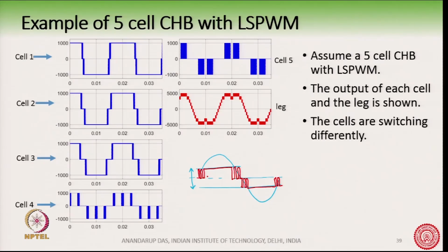Cell 2, for example, is taking this part of the waveform. So, it will be switching here and then it will subsequently get clamped, and this is what cell 2 is, shown here. You see this part till this part, so it means cell 2 sits over the top of cell 1 and subsequently cell 3 sits over the top of cell 1.